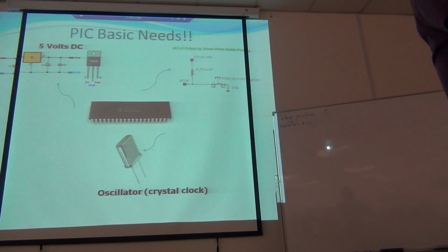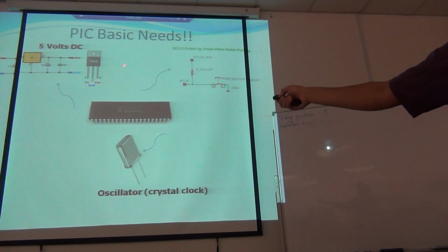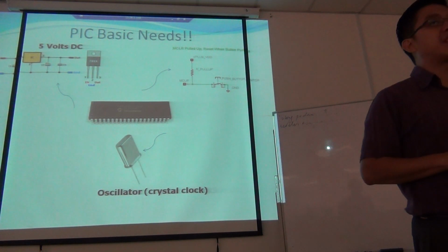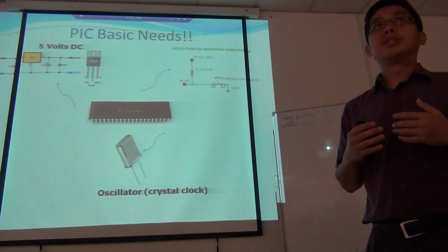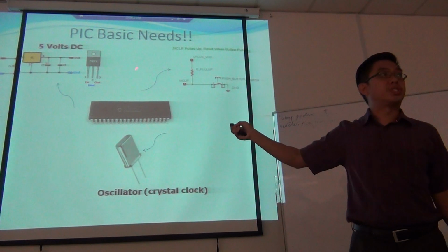I recommend that if you have your team later, you can bring your own multimeter. It's much better to understand. Alright, if you plug in, that is the source for your 5-volt line. The converter starts from 12 volt, if I'm not mistaken. Let's look at the setting of your converter. Is it 12 volt? Normally your converter will give a higher level of voltage. Then it will go through the board by this 5 volt circuit.